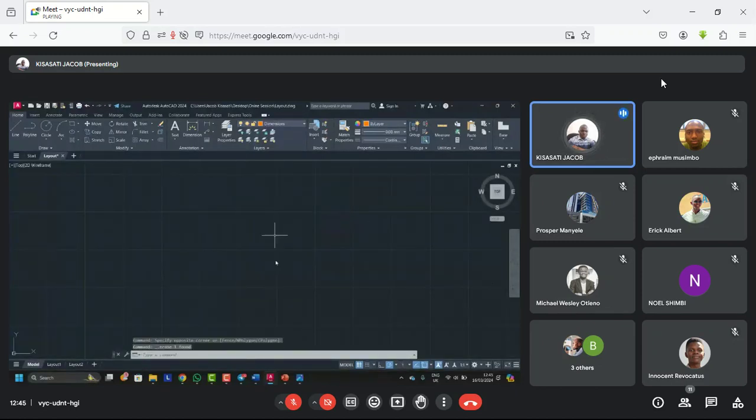Let me just delete this one. You can just be using the picture itself. Now I'll create this one, and the first thing is to turn on the layer, the grid line layer. Sorry for that. Turn this line on. Then I'll draw this line, the perpendicular line, in Y direction like that. So I'll just make sure my ortho is on, orthogonal.